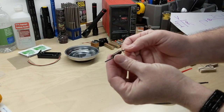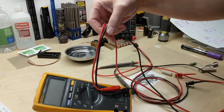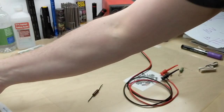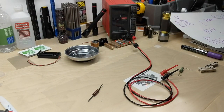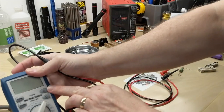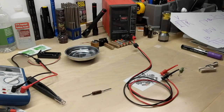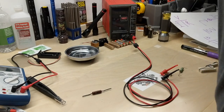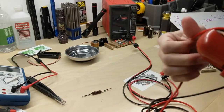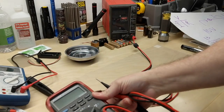If we wanted to check this 1 ohm resistor, I would get my 179 out, and we could still do it with the 179, but it doesn't have the relative mode. So either I could use this little BK Precision, which does have a relative mode, where we can zero out the leads. This one, the Fluke 87, also has a relative. This is actually one of my earlier Fluke 87s.